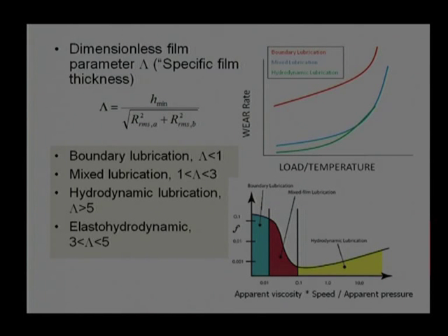For the same load condition and a different area condition, if I assume, we always find the wear rate in the boundary lubrication mechanism is much higher compared to the hydrodynamic and mixed lubrication mechanisms. So, we should avoid boundary lubrication as far as possible. We should provide some lubricant one way or another.